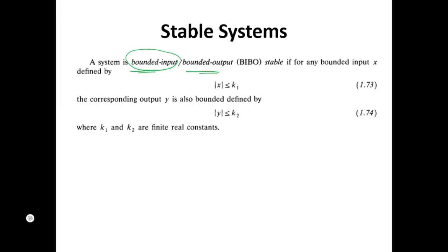Now if they get saturated, that means suppose any amplifier is being operated under a DC voltage. Dual DC voltage, say for example plus minus 12 volts. So when you are having this plus minus 12 volts, under ideal condition, what should be your maximum limit?